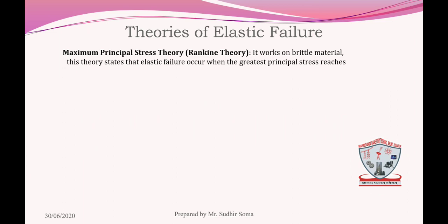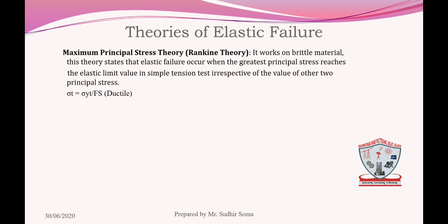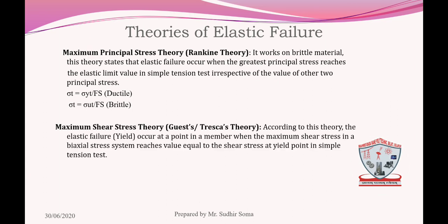So next slide, you see the theories of elastic failure. You know there are a number of machine components that are subjected to several types of loads simultaneously. Combined stresses are induced in them, such as torsional shear, bending stress, etc. Mainly, the failure of such components is classified into two groups, that is elastic failure (yielding) and fracture.